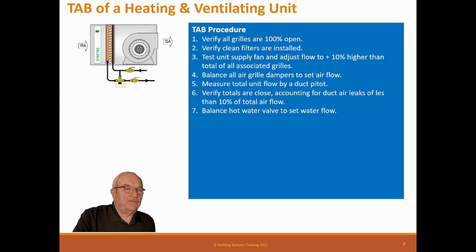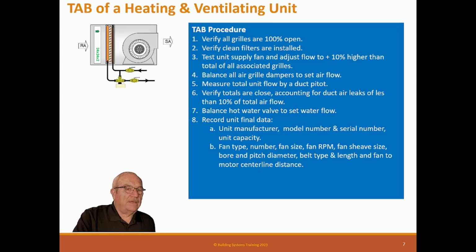Balance the water valve to set the water flow. Record the final data, which would be the unit manufacturer, model number, serial number, unit capacity, fan type, number, fan size, RPM, sheave data, bore, pitch, diameter, belt type and length, and fan motor center line distance.